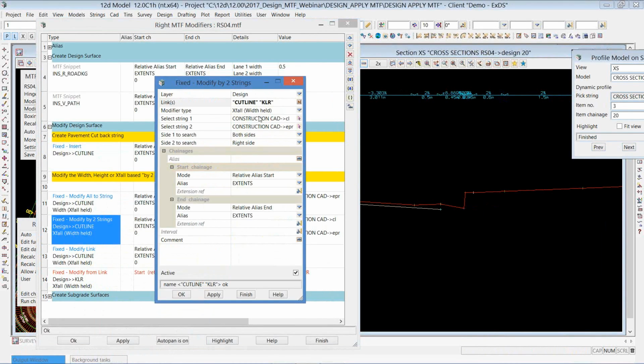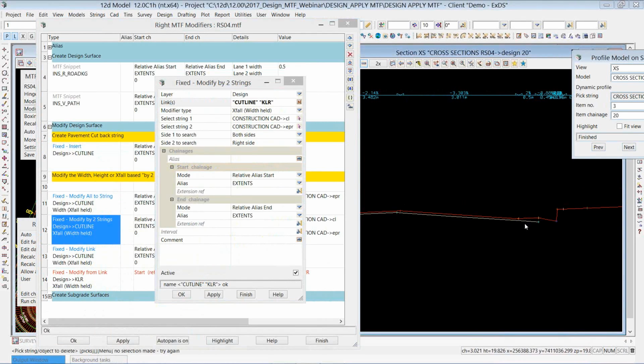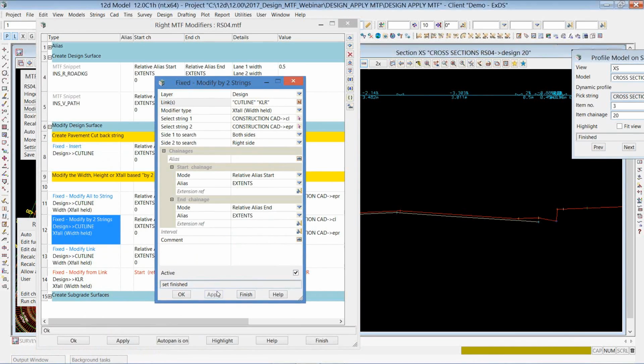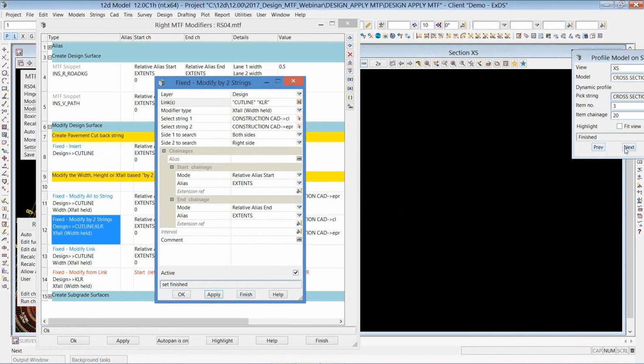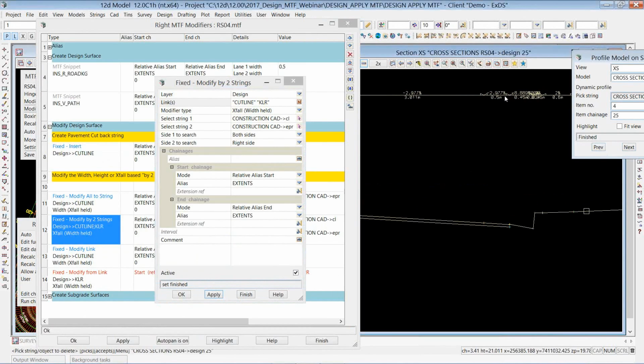So in this one again, I'm taking the 2 answers, the string crossfall from the 2 original surveyed strings, and I'm applying it to my designed cutback line, cross-section, crossfall, and also the lip of the curb there. So I can kill 2 birds with 1 command, and that's exactly what I've got. So I've got 2.9% there, and again 2.9% there, and they're both matching the existing crossfall that was picked up in the design. So that's done a couple more of the commands for us.